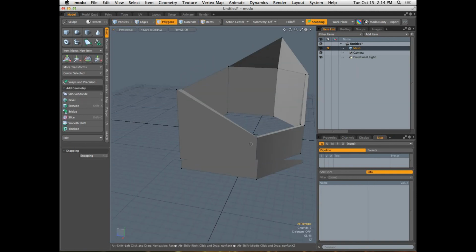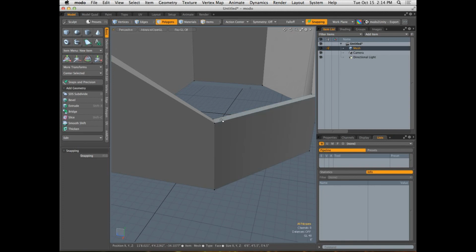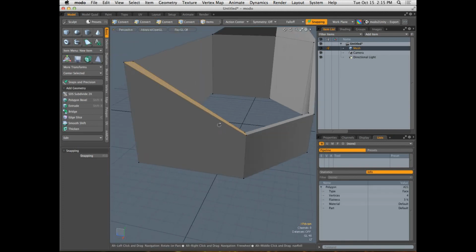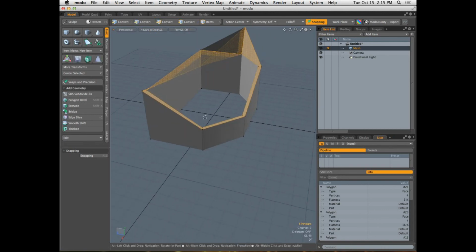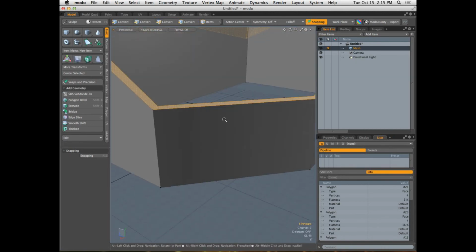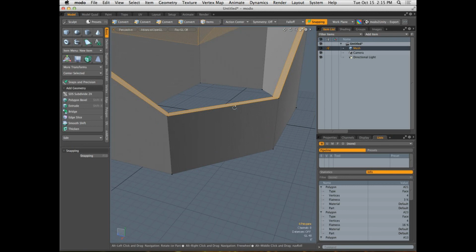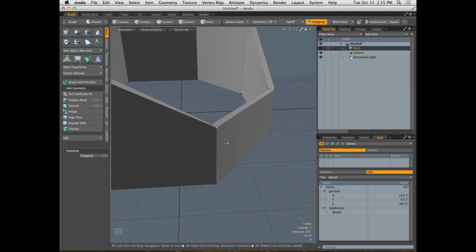Check it out. So maybe I want all the polygons along the top of my wall here, all of these guys, to be that height. So the height of this one right here. Well, I don't know what that height is, okay? I have to do it mechanically. So if I go in, select that vertice, the Info tab is going to tell me right there what the height is. Okay, so it's 4 feet, 5.5 inches. I'm just going to copy it. Command-C, Control-C for you guys on a PC.